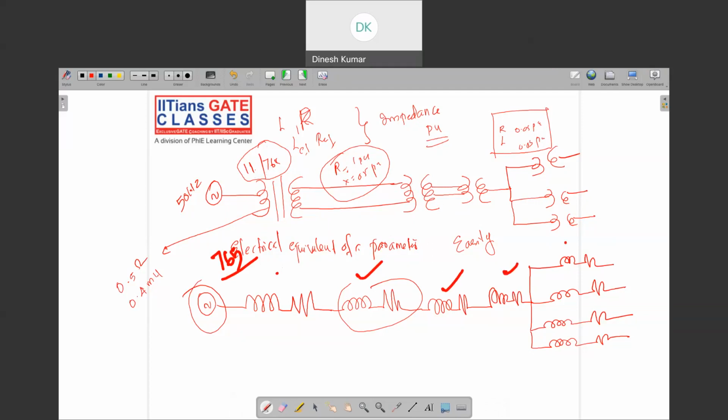So write everything in per unit. If you use base changing, then change the base for everything and make it a common base and do the calculations. At the end, if you want to find the voltage drop across this transmission line, find the per unit voltage across this transmission line, then multiply with the base voltage, right? So that means it gives you more freedom in doing things, and more easily.